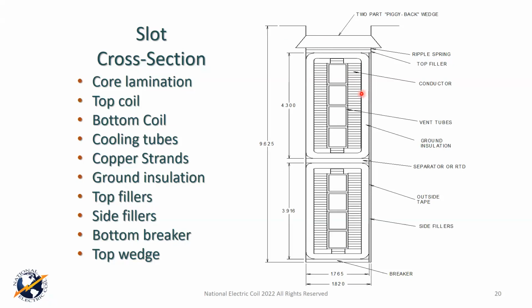Winders would often immediately refer to what's called a figure-8 tie. And as that side packing is put in, one of the winding processes they'll put in, and it can be put on later, is they would put a tie that goes around and snakes around this way and then comes up and puts around. And at the top up here, they tie basically a square knot.